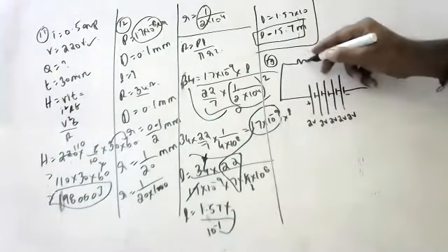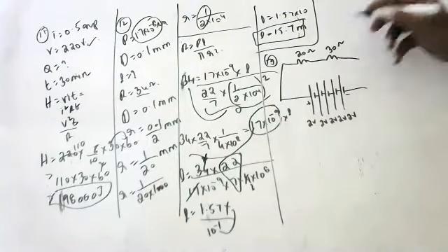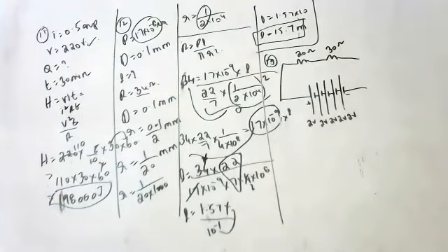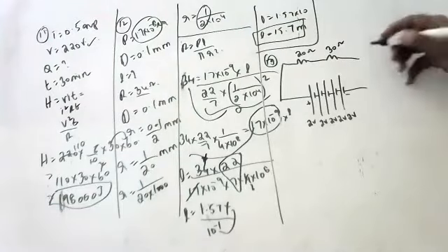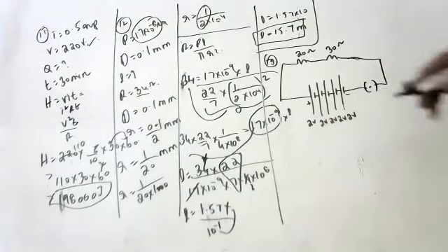Consisting of a 20 ohm and a 30 ohm resistor, and anything else given? 20 ohm, 30 ohm, and plug the key. They want the plug key also, children. Plug the key means it looks like this. If you put a dot, current is going. If you don't put a dot, current is not going. Your wish. Calculate the value of current flowing through 20 and power in 30.